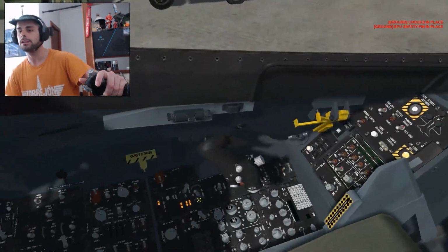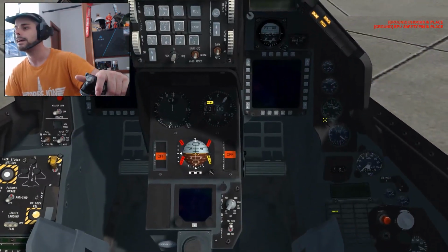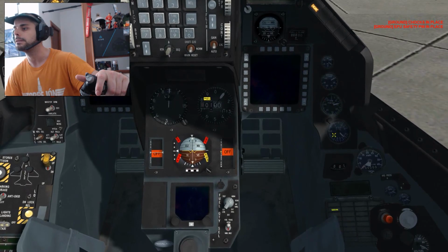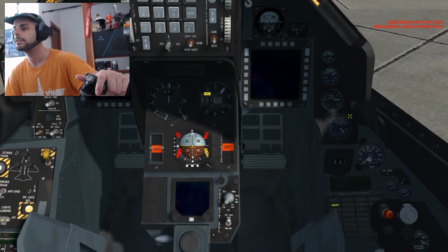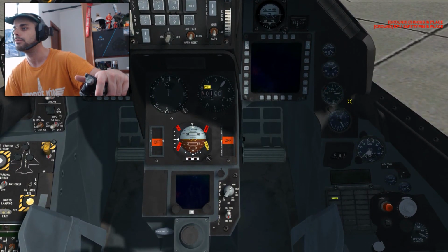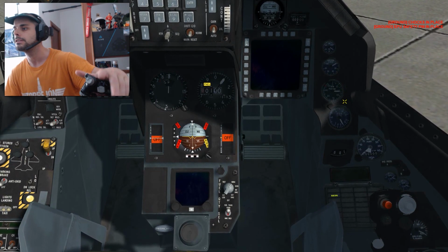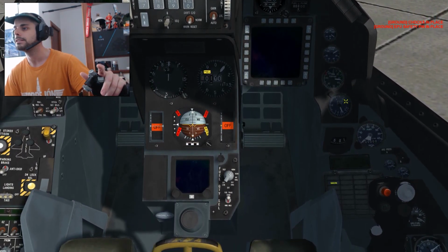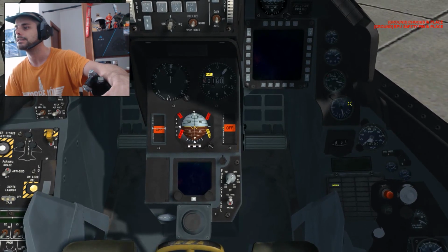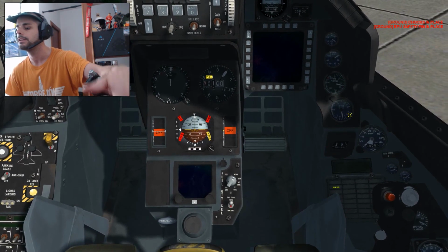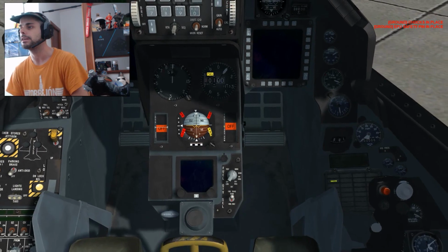You can move the throttle forward a little bit. And also check RPM, temperature, oil in the future. Now that we are around 30, 40, the throttle goes back. Check temperature. Slow movement is always good. Okay, as you can see, let me pause a moment.